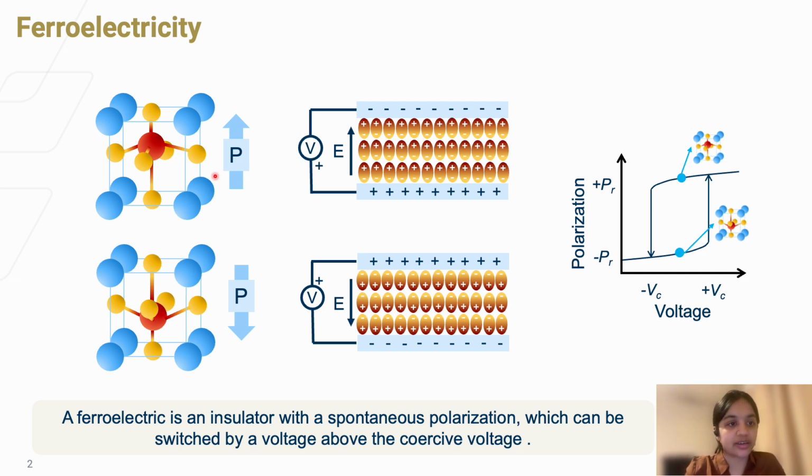of the material, that is, what is ferroelectricity? So these are non-centrosymmetric crystal structure materials. That is, if you have a crystal structure that looks like this, if the center atom is pointed upwards, we have the upward polarization, and if the center atom is pointed downwards, we have the downward polarization. And we can sandwich this material between two metal electrodes and apply an electric field and switch the polarization between the two states. And that's how we get this hysteresis loop over here.